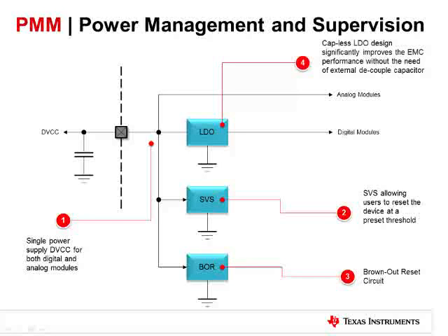Lastly, there's an integrated LDO for generating the core voltage. You can run at any frequency all the way to 1.8 volts, and there's no configuration of different core voltage levels. There's also no external capacitor needed, saving cost and board space.